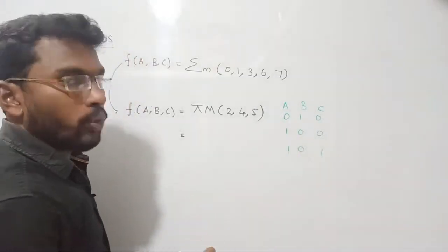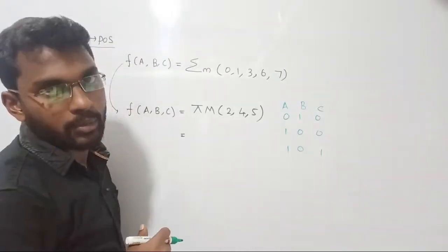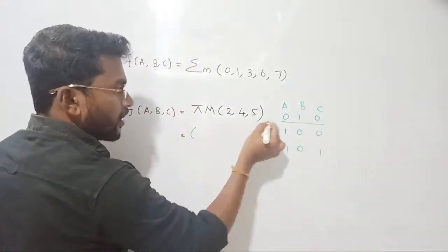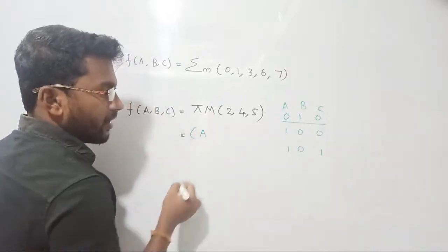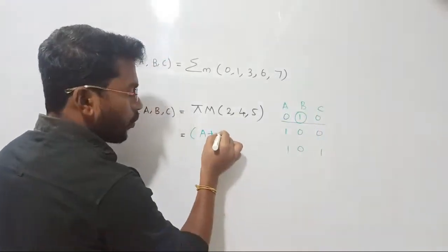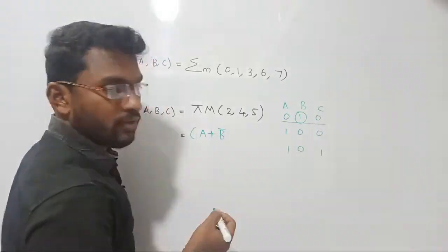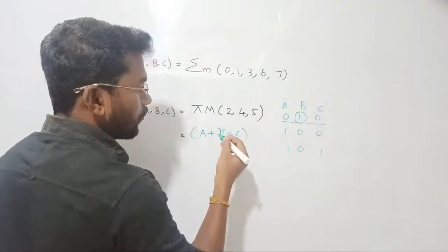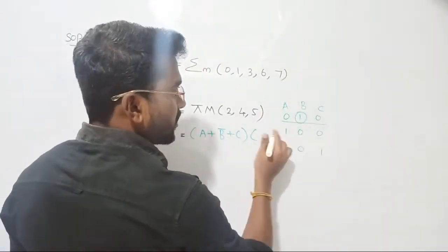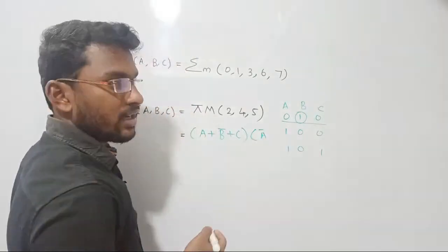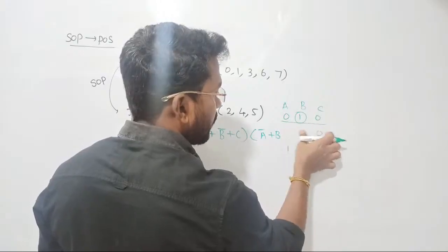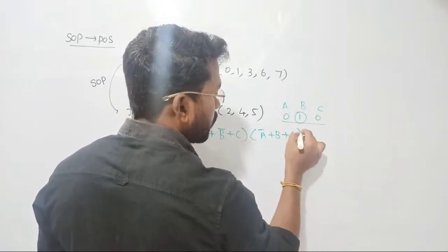If you want to write 1 in max term form, then we should take the complement of it. If I group these three together, how will you write? For 0 we can directly take variable A and then perform the OR operation. B is not directly acceptable because we have 1, so we have to take its complement, and then C is acceptable, of course. Similarly, for the second one, 100, this is going to be A bar, since 1 is not acceptable, but B and C we can directly group, because both are 0.